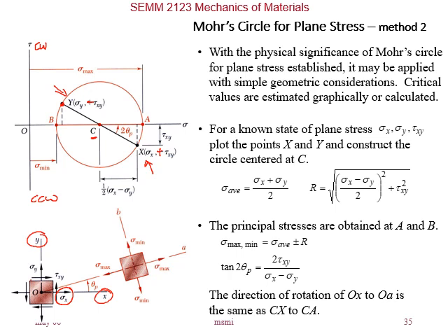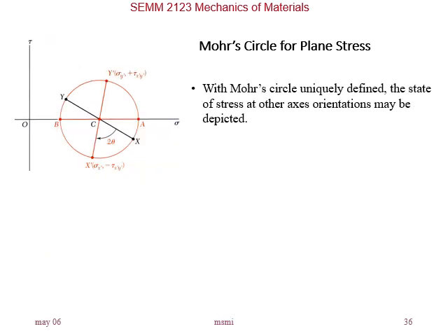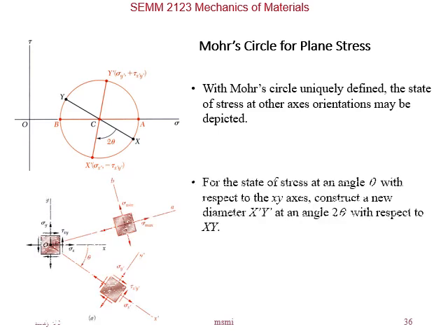Okay, so that is again a Mohr circle. So what we then have is, for example, if you look at this circle here, now this is your reference, that's the x-axis, right? A is the maximum value of principal stress 1, so that is sigma 1 or sigma max.